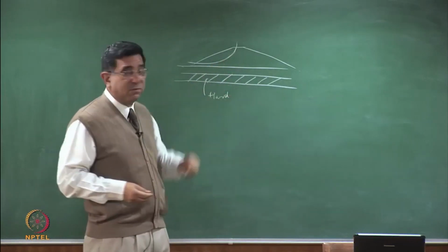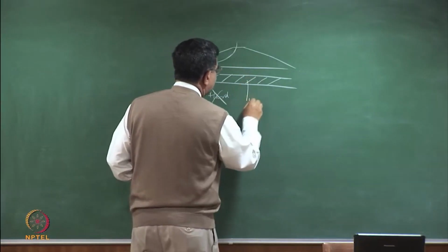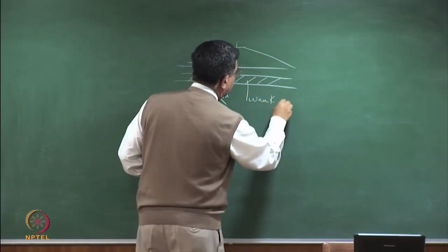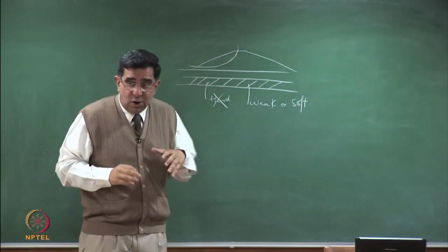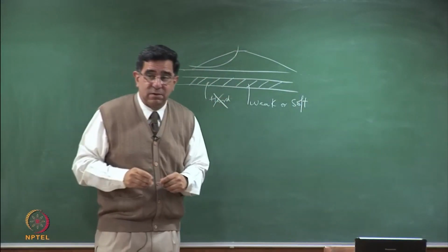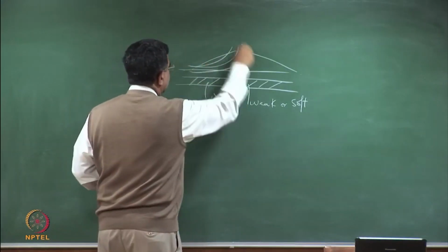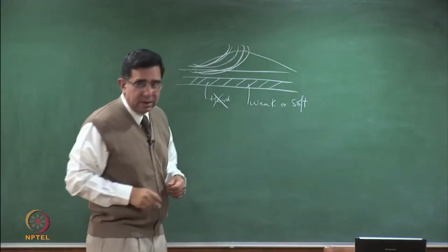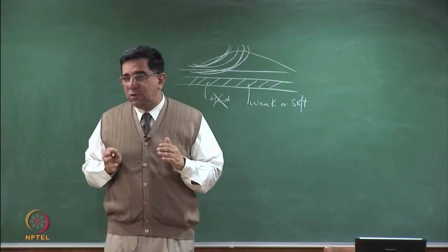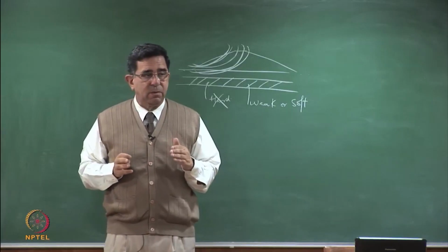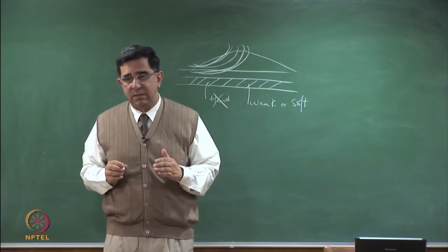So if I have a weak surface here, weak or soft, then this failure surface might be drawn towards it, may not necessarily be the critical failure, because you are doing a lot of circles. As we said, to find the critical factor of safety, you will have so many circles which will be done. So which is the case in which you definitely get weak surfaces, and you have to try for straight line analysis as well.